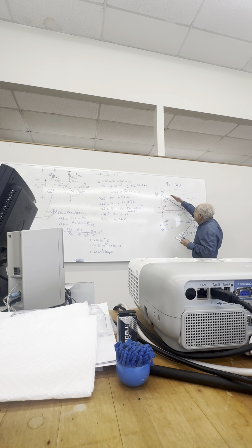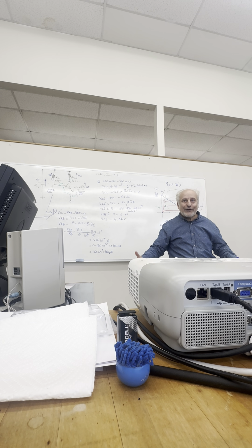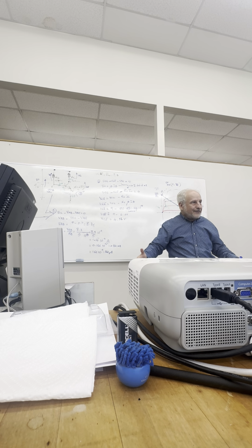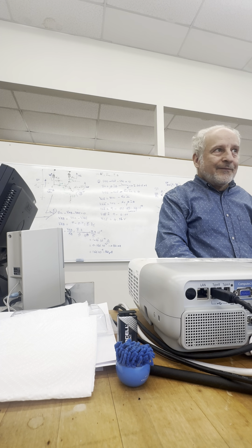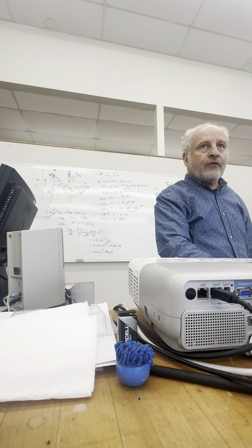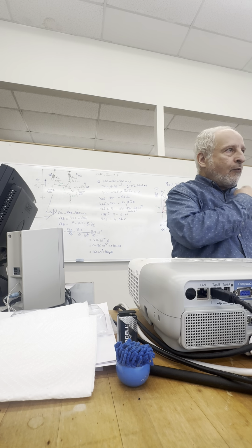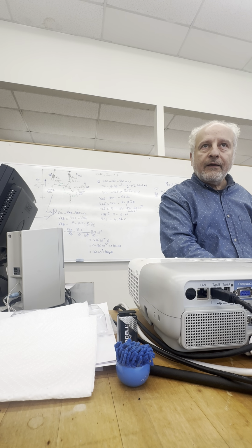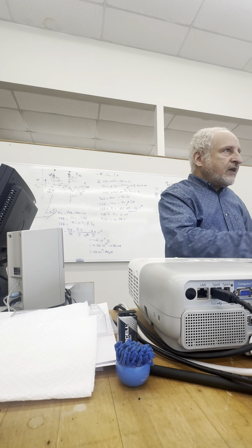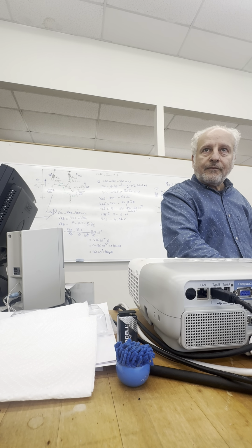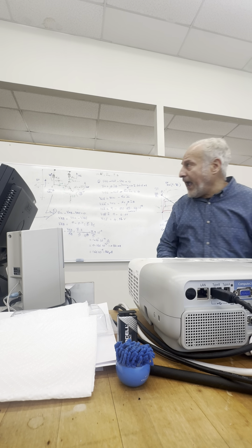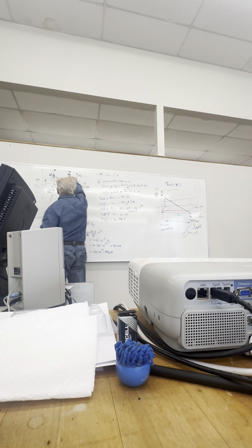Now, how do I control this line? Well, I have full control over that, over VCC and RC. That's my external devices, regardless of the transistor. I choose what VCC and RC will be. I get a 2 or 2, and if I want the same load line, it doesn't matter. I can get it, because that's dictated by the RC and VCC. Does that make sense?